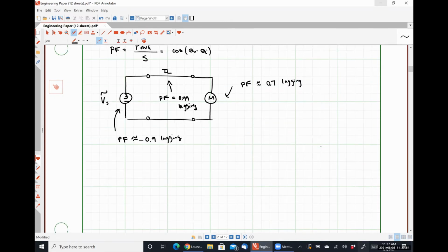As you've noticed here, power factors are classified as either lagging, which is all we've talked about so far, or leading. We can describe this mathematically: if our angle theta_s is between 0 and positive 180 degrees, we have a lagging power factor. And if our angle is between negative 180 degrees and 0, we have a leading power factor, right?